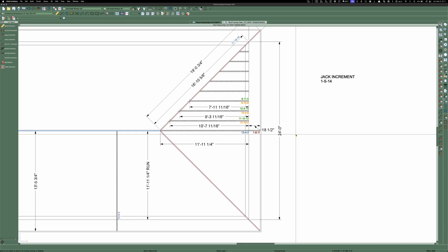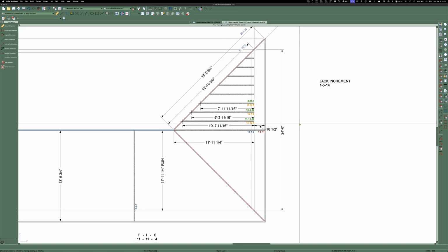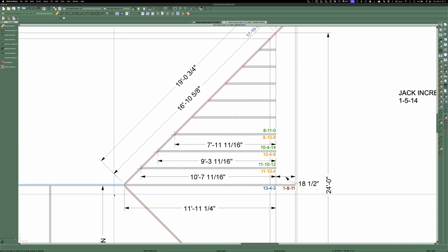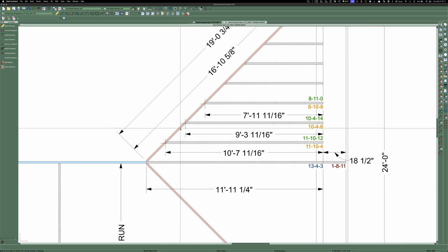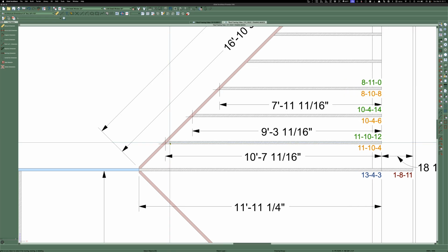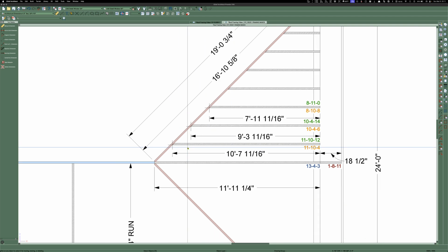All right. So I hope that helped anybody. I hope I didn't really confuse you, but the variable you need to know is how thick this is. If you're using an LVL that's 1 3/4 inch, that actually helps the Construction Master be closer, because now you're bringing the face of the hip closer to that shorter jack. And so your jacks won't run as crooked.